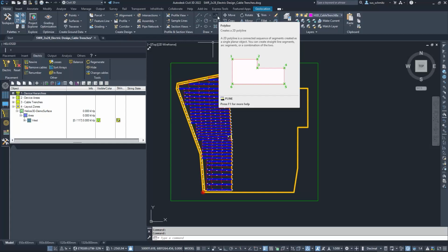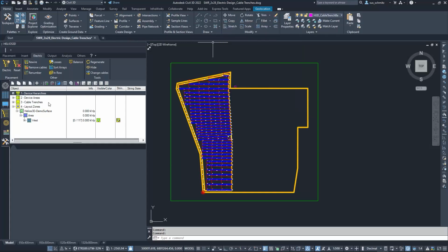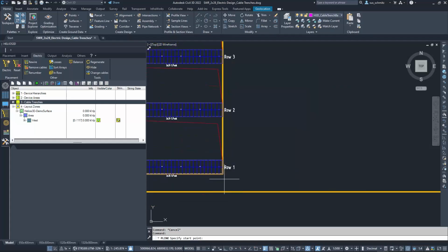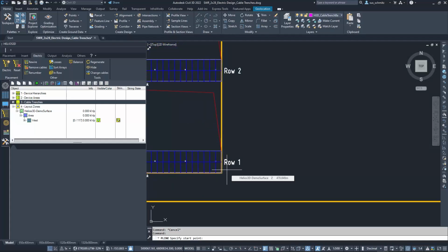We will start with the trenches through the table rows. I start drawing the trench and zoom to the south of the field. For the row to connect to the trench, it's important that a virtual line through the middle of the row must find an intersection point with the trench. So, I start the trench in the lower half of the first table.